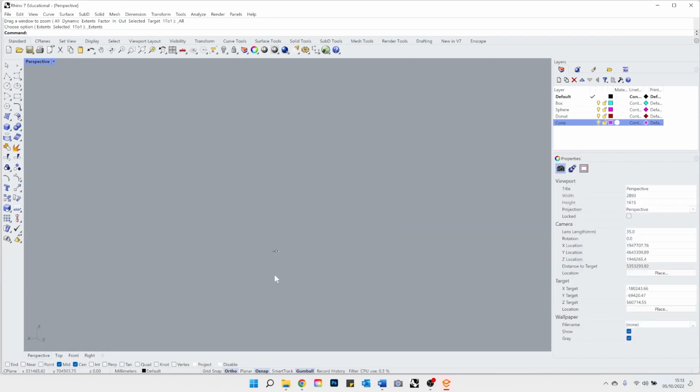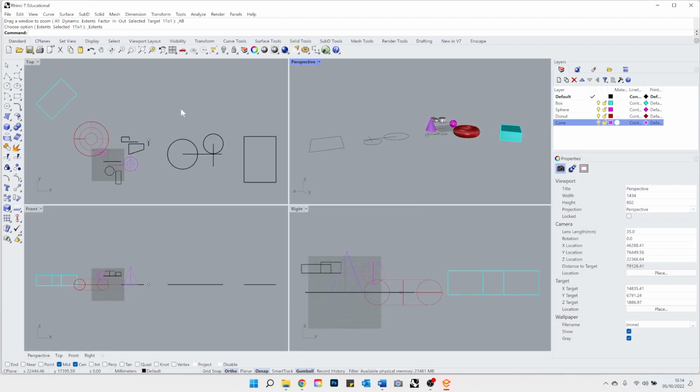Or again, there is a different option. If you're too far and you want to zoom in to see your whole model, or maybe you're too zoomed into one object and you want to see the whole thing straight away, ZEA, so again three letters. Without having anything selected, ZEA is going to show you the whole model on the screen. But zoom selected all, ZSA, is absolutely brilliant.